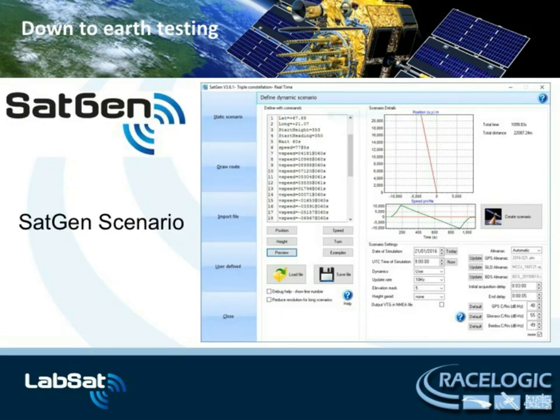We therefore worked closely with them to develop an identical trajectory with artificial satellites using our FatGen signal simulation software. In the process, we had to make quite a few modifications to make it more suitable to the high dynamics and high vertical climb rates required by their test. We started off using their recorded NMEA file to exactly reproduce the trajectory of their recent test using artificial satellites and signals. We then fed this scenario into a LabSat 3, which provided the signals to their Novatel receiver, which then successfully locked onto the RF signal and followed the same trajectory.